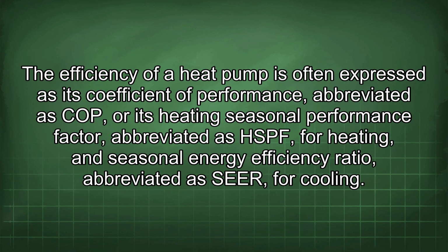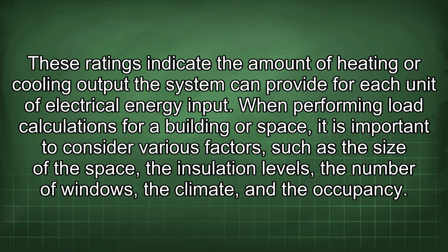The efficiency of a heat pump is often expressed as its coefficient of performance, abbreviated as COP, or its heating seasonal performance factor, abbreviated as HSPF, for heating, and seasonal energy efficiency ratio, abbreviated as SEER, for cooling. These ratings indicate the amount of heating or cooling output the system can provide for each unit of electrical energy input.